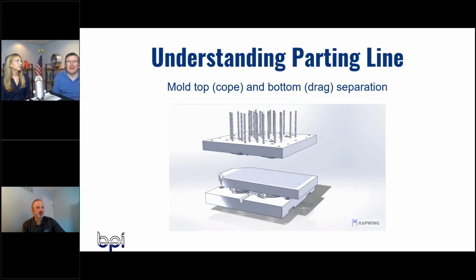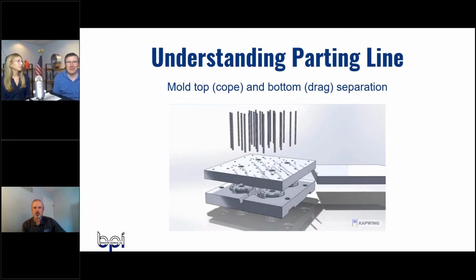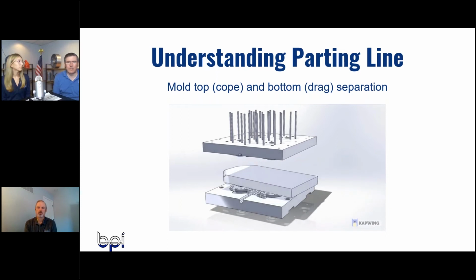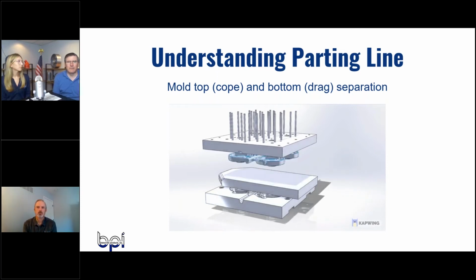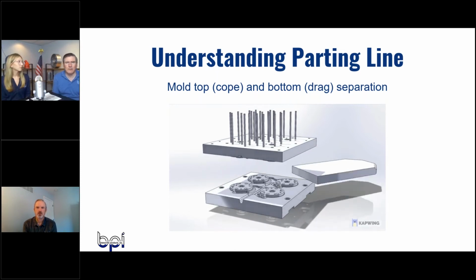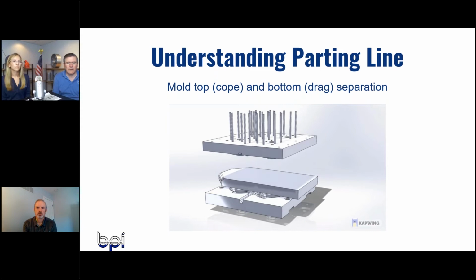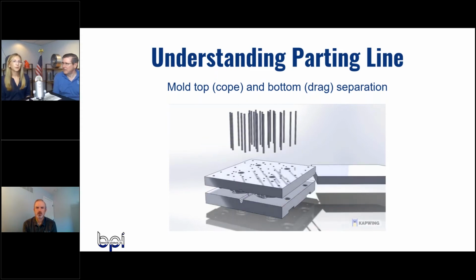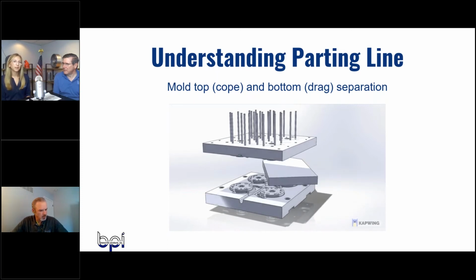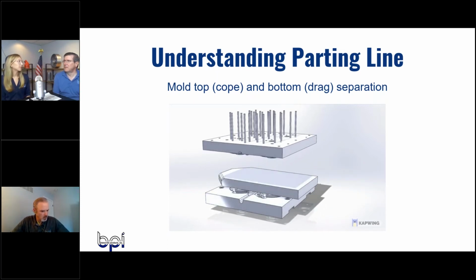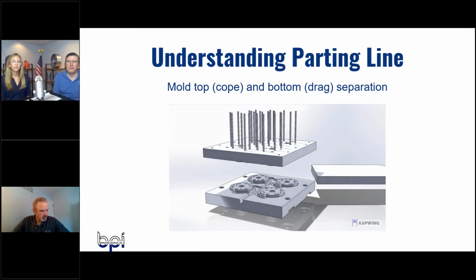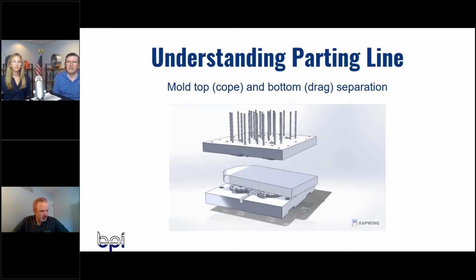I don't know the exact counts, but it's quite a few parts. The permanent mold process is a great, fast and efficient method to produce parts in relatively large quantities. So say if you cast 1,000 parts a year for this product line, you could look at your mold lasting up to 12 years, and that's a good life of a tool, right? Sure, you bet. That would go easily to 12 years, I would say.